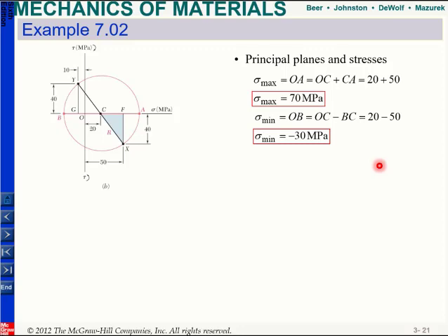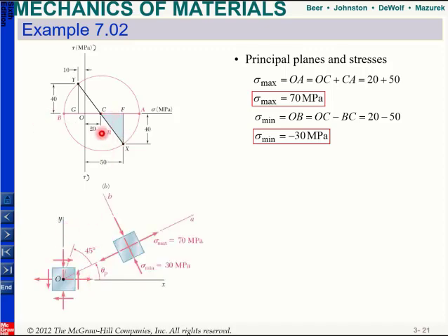If you look at the angle, I need to rotate it. So I need to find this angle, the angle between CA and CX. It will be equal to 2 theta p. Here I need to rotate it. If I want to move X to A, I need to rotate it counterclockwise. So this is why I also rotate it counterclockwise.